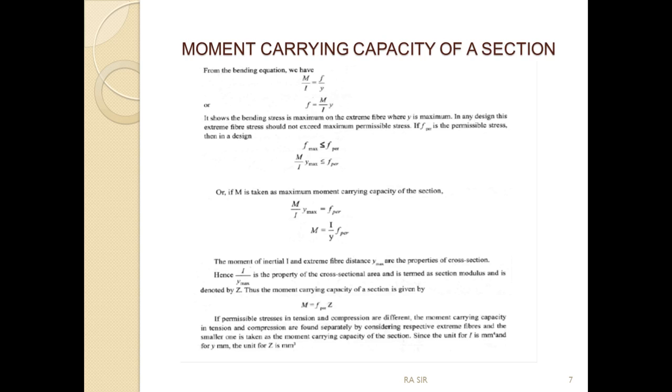That means the permissible stress will be the highest limit for any particular section, and it will always be greater than f max for that section. So f max will be M by I into y max, which is less than f permissible. If M is taken as the maximum moment carrying capacity of the section, then M y max by I equals f permissible.